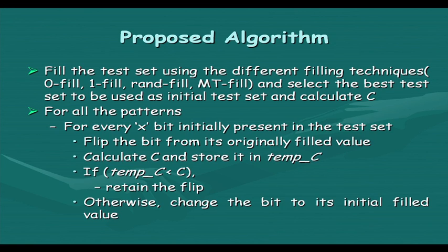So, it is a very greedy technique. It starts with the best possible filling pattern out of these well known filling patterns, 0 fill, 1 fill, random fill, MT fill, and then it tries to change every x bit to its complement value and see what is happening to the criticality value. If the criticality value is improving, then it is accepted. We will continue in the next class.